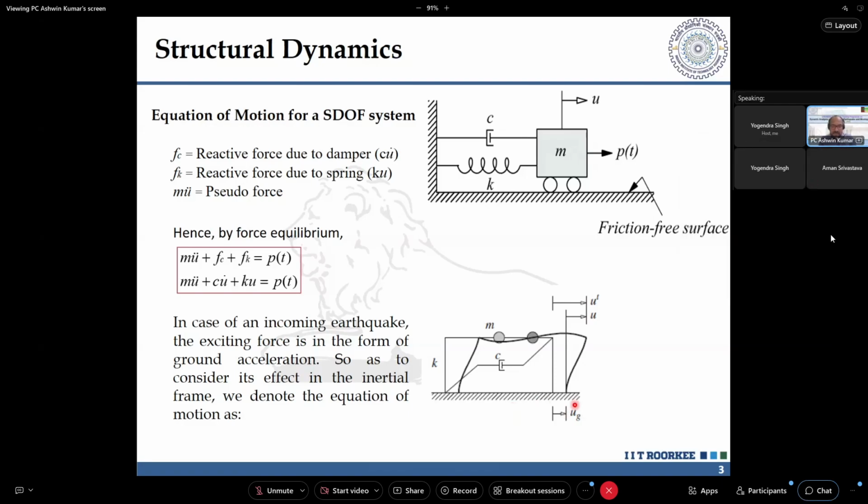So we have a rigid ground body displacement that is happening here, then a relative displacement that happens in the members of the structure that is creating the reactive forces. The reactive force due to the stiffness, or the forces generated due to the damping, cannot be generated if it is a rigid body motion. There should be some relative motion generated. So during a ground motion, like inertia, we all know the example that our teacher says: when the bus moves, we feel ourselves being pushed back. So when the earthquake comes, let's say left to right, the structure moves from right to left, and that creates an inertial force that is generated in them.